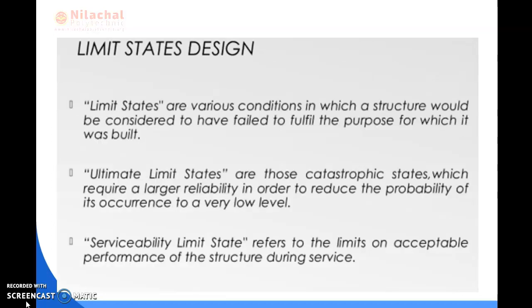Then we discuss what limit state design is. Limit states are various conditions in which a structure would be considered to have failed to fulfill the purpose for which it was built. Ultimate limit states are those catastrophic states which require a large reliability in order to reduce the probability of their occurrence to a very low level. Then we discuss the serviceability limit state. It refers to the limit on acceptable performance of the structure during service.